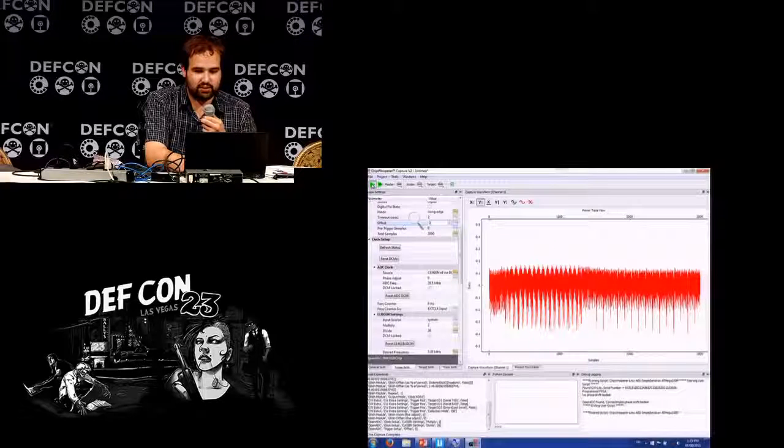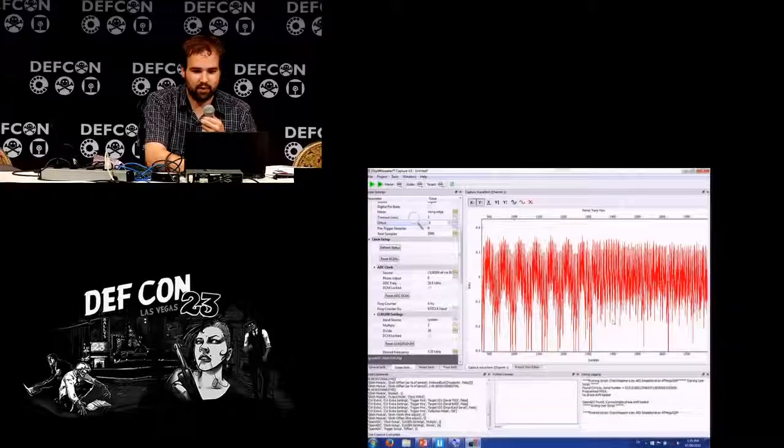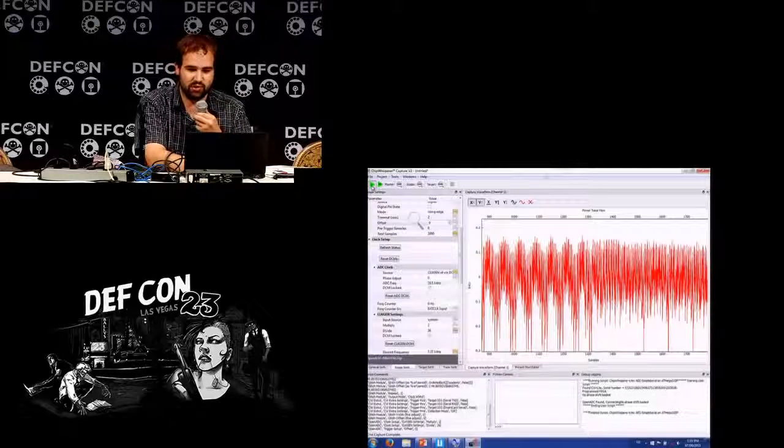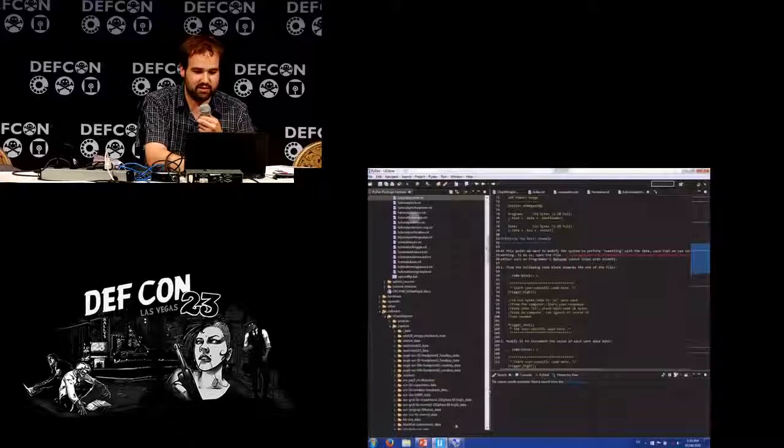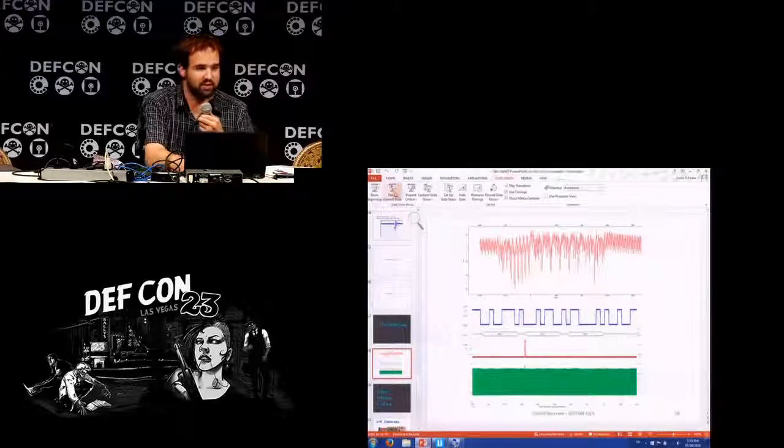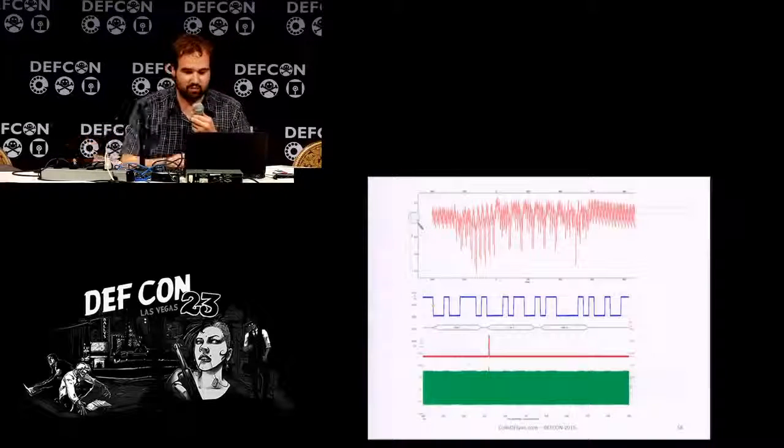So as I hit capture, there's this section in here, and you'll notice the data doesn't jump around for like the second half. There's a little section in there. So you can actually trigger based on a pattern in the analog data. So that's something that some of the ChipWhisperer hardware variants, not the Lite, but other ones, can actually perform.